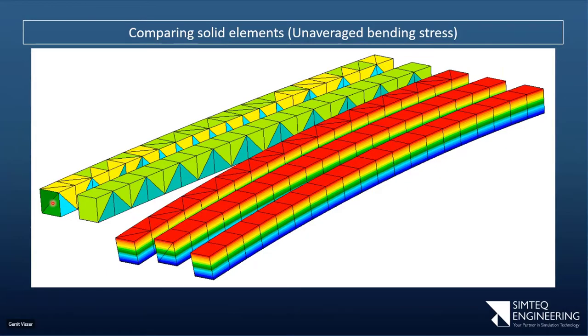This one, the tet mesh, will always give bad answers unless you have a very simple, close to constant stress state. And in addition, for this one, this is where we need to have more than one element through the thickness. The more the merrier. So at about 3, you'll start getting reasonable answers out of this.